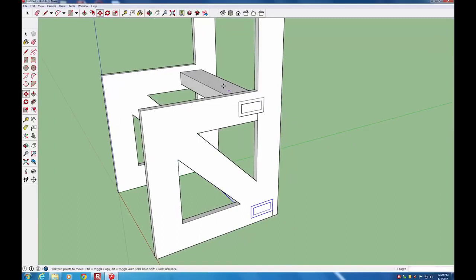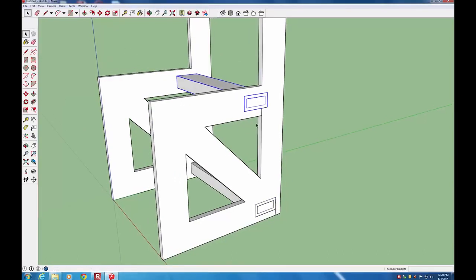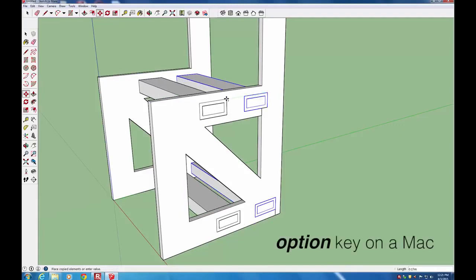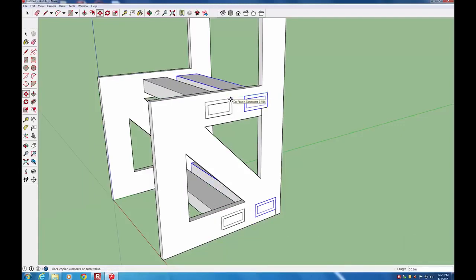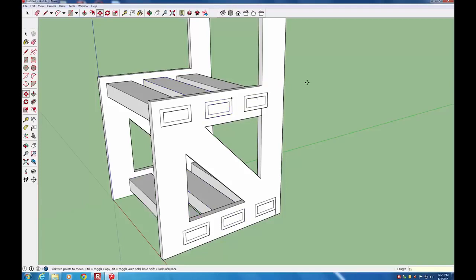So next we want to make several copies of these rectangular tubes moving forward. So we're still in the Move tool, but I'm going to go to the Select tool and select both of them, just with a click and then Control, click. So now you can see that both the rectangular tubes are selected. Go back over to the Move tool, click anywhere on them, Control, click. I'm going to slide it over, making sure that we're staying flat along this face. And I'm going to move it 0.15 meters, so I type in 0.15 and enter. And I actually want to make not just one copy, but two copies. So then next you can just type in 2x and enter, and it'll double that.